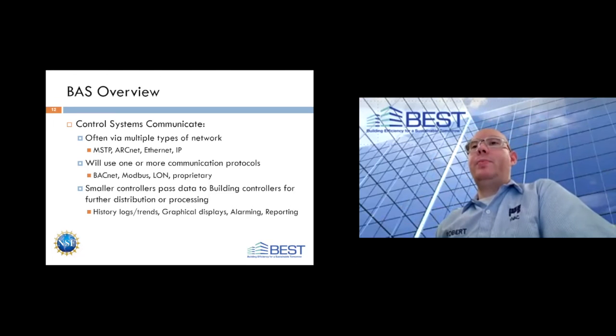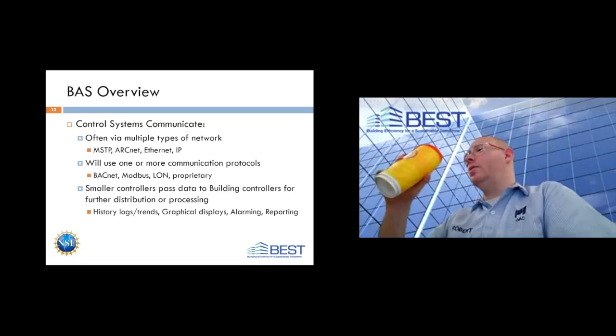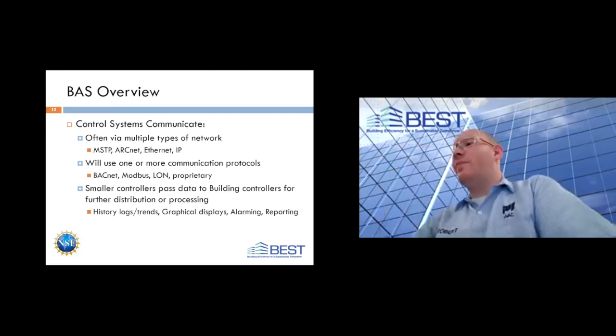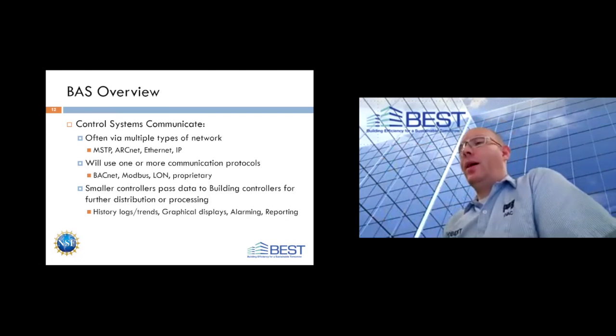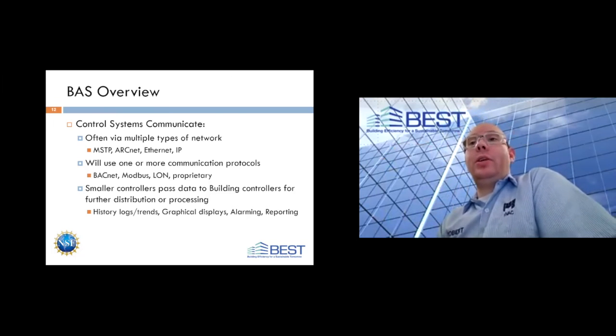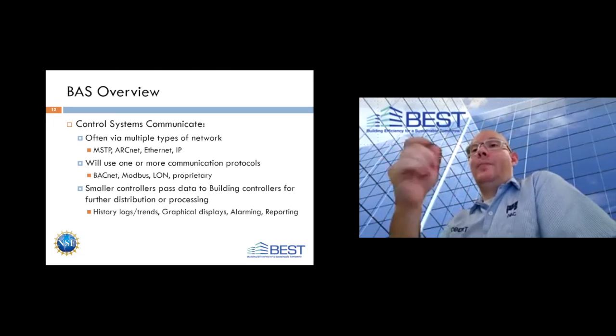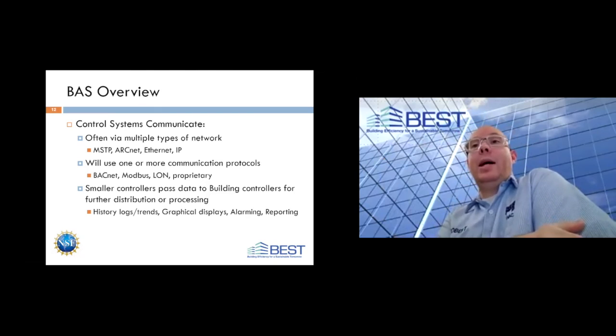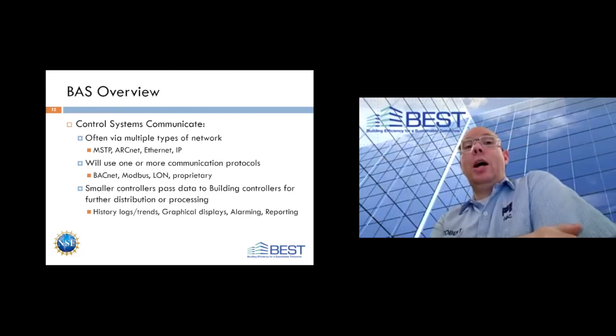That's been something that's developed mostly within the last 20, 25 years. As our systems advanced, back before we did electronic controls or DDC, direct digital controls, many of our climate control systems especially were pneumatics, and we had very little visibility into the system. If we wanted to know what an air handler was doing, we walked over to that air handler and looked at the gauges that were built into it, or took out our temperature probes and analyzed the system from that standpoint. So we've come a long, long way.